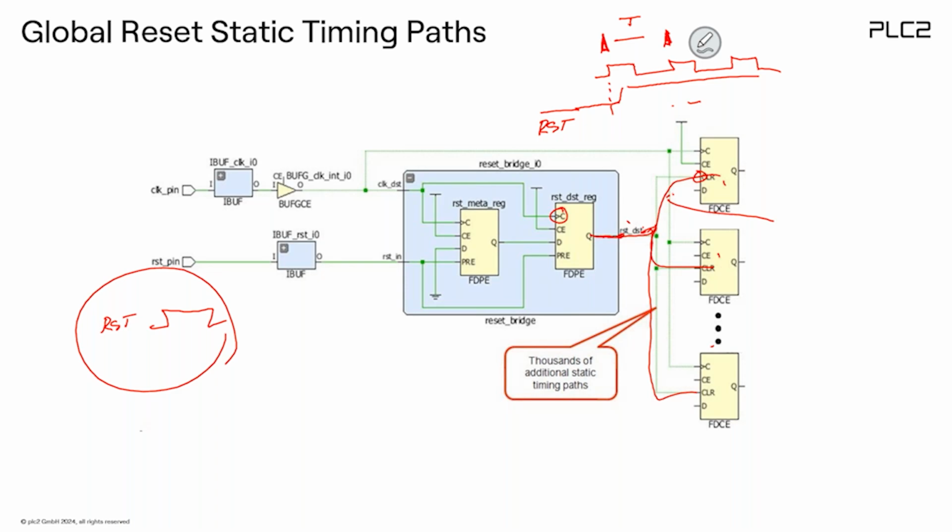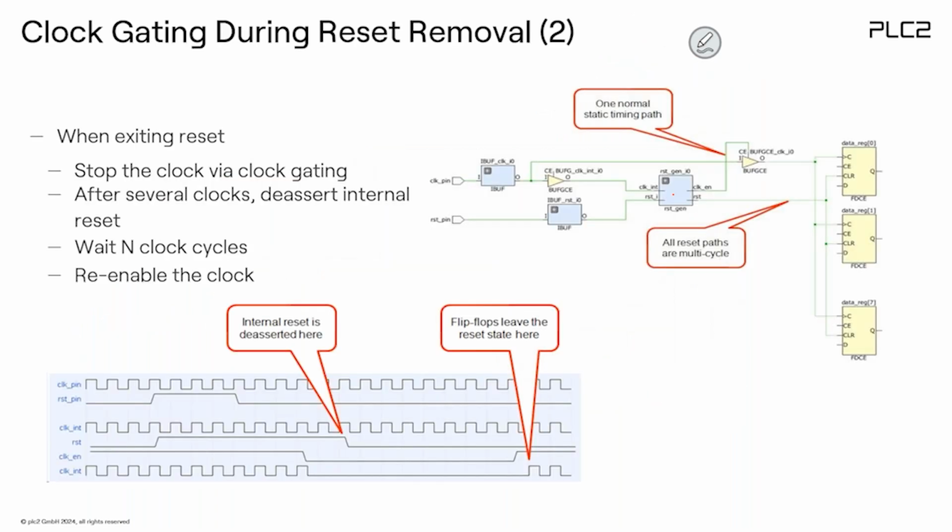So what could be the alternative is something like this. You just do so-called clock gating. You have the reset. You just activate the reset, and a reset generator is doing this. Whenever you activate the reset generator, it just switches off the clock.